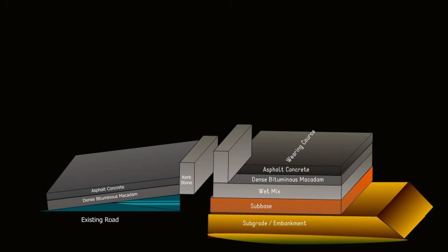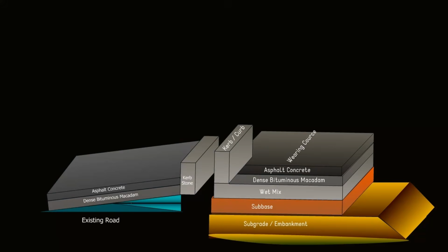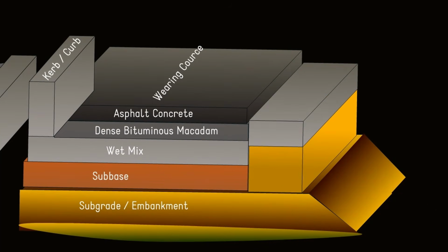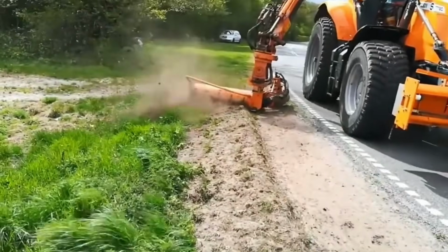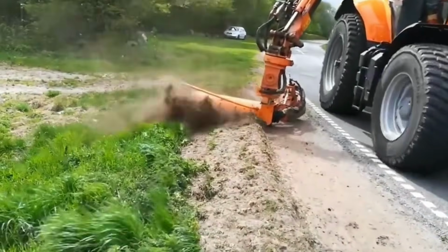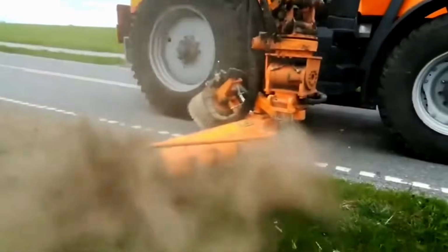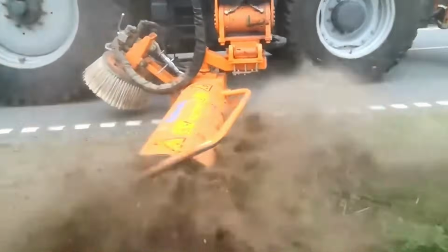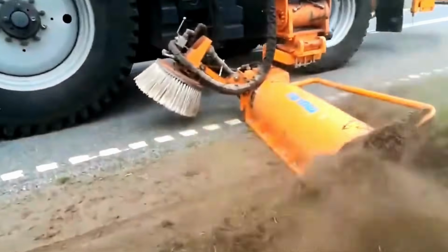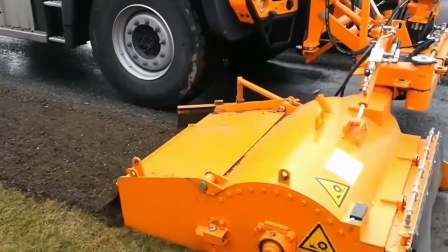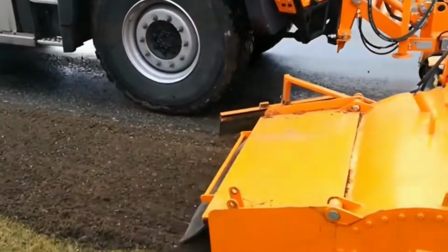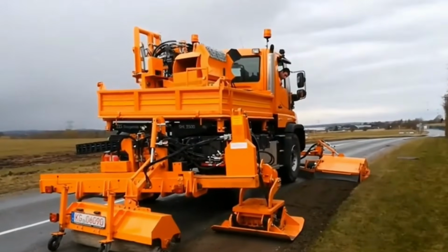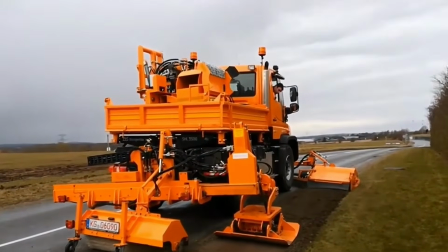The next item of work is shoulders. Shoulders. The shoulder is a necessary part of highways and it serves several functions. It provides lateral support to the highway pavement. It helps protect the highway surface from the intrusion of water, which is one of the major causes of pavement damage. A wide shoulder also provides a temporary parking area for vehicles, allowing people to stop when required.